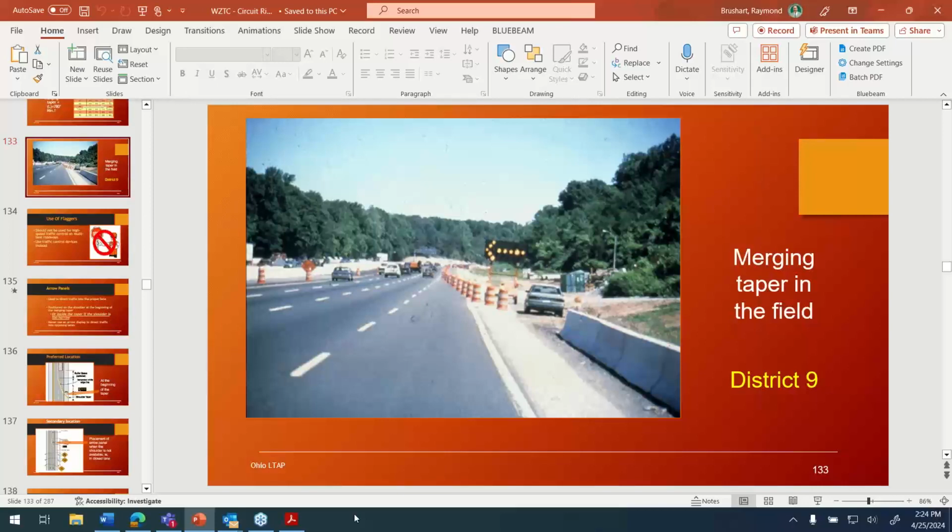Well, Ray, they might need some additional information. Okay, when you're looking at the typical application, you know, that vacant area, let's work our way south. That vacant area south of the pothole, that's called the buffer space. So we need to add up the length of the buffer space and then the 100 feet for the taper. And then we got to add up A plus B plus C. So it's a lot bigger number than 900 feet.